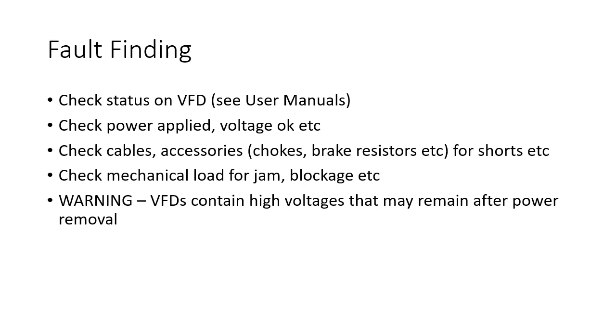One important point is that VFDs contain very high voltages internally. It's not recommended that you start taking the cover off a VFD and fault finding inside. That's normally a specialist function. Because of the way the voltages are chopped up and the way capacitors are used for doing that, those high voltages can remain for several hours or even longer after the power is removed from a VFD. So be very careful when you're doing anything inside the VFD itself, and it's best left completely alone, because those voltages are very, very high.